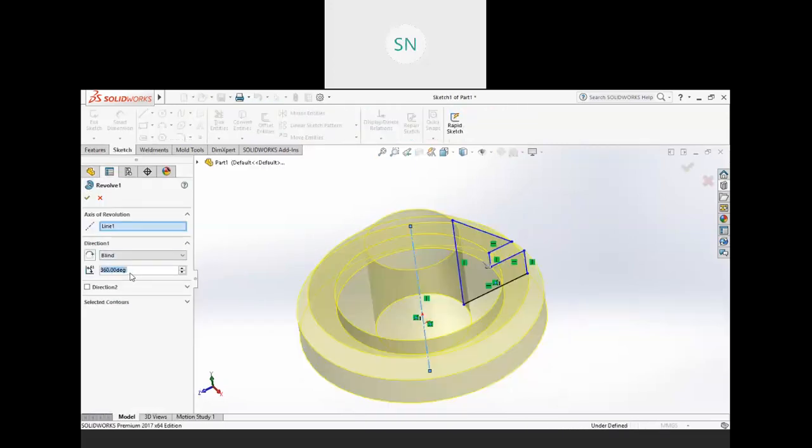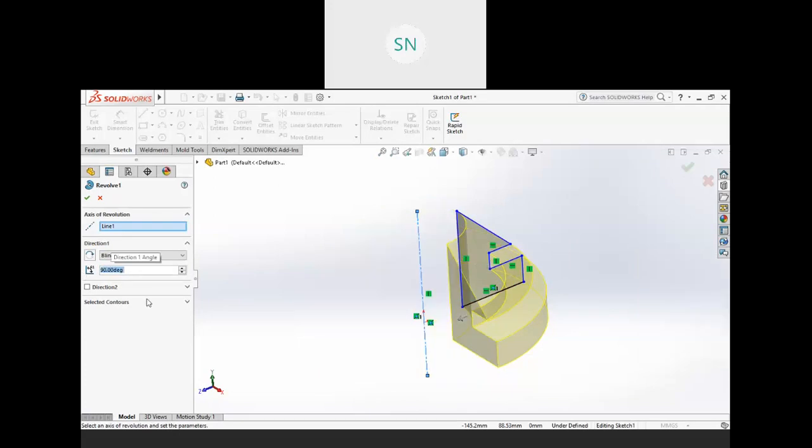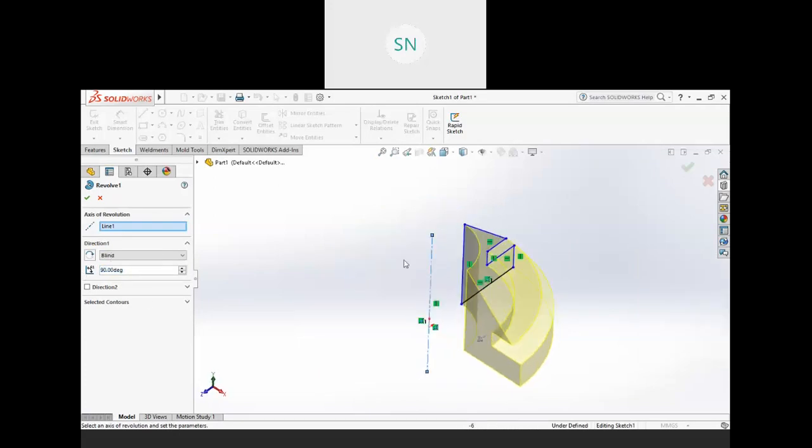So here instead of height, see, in the extrusion operation it will take a straight height over here like this, right? But in the revolve we have degree over here, see, degree angle, let's say 90 degrees. In this case, this sketch is taking an angle around this axis and creating a solid like this.